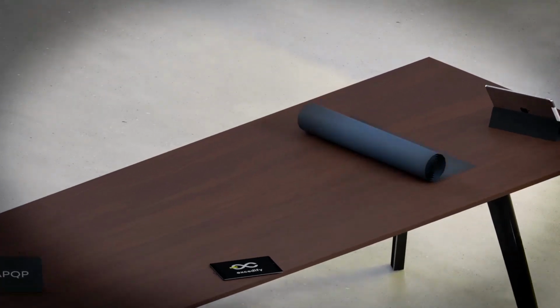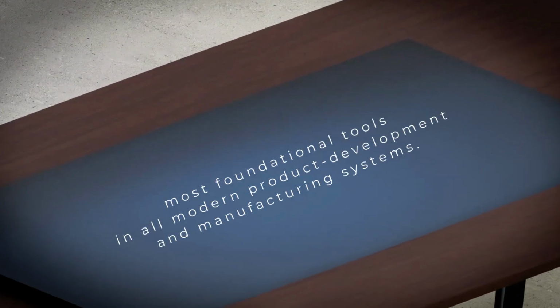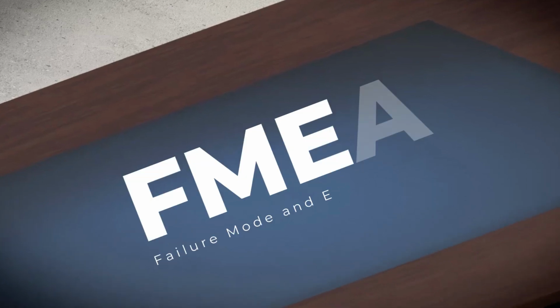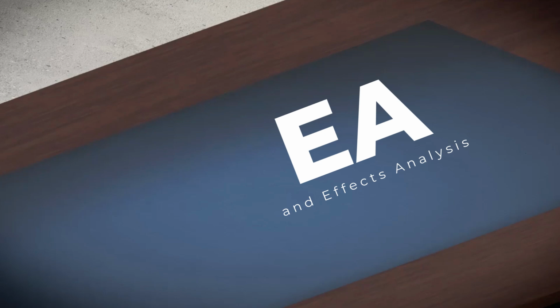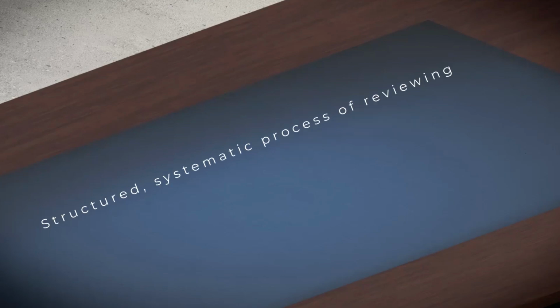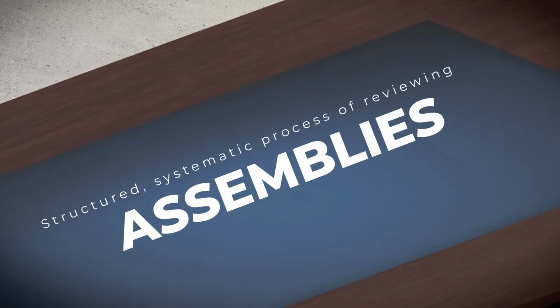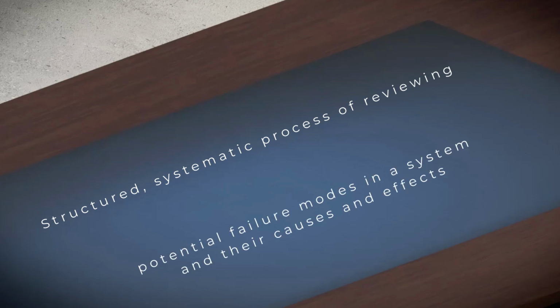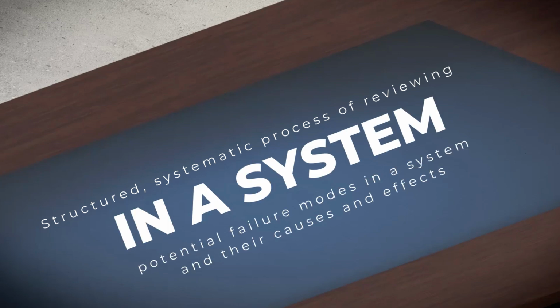Today we're going to break down one of the most foundational tools in all modern product development and manufacturing systems: failure mode and effects analysis. FMEA is the structured and systematic process of reviewing as many components, assemblies, and subsystems as possible to identify potential failure modes in a system and their causes and effects.